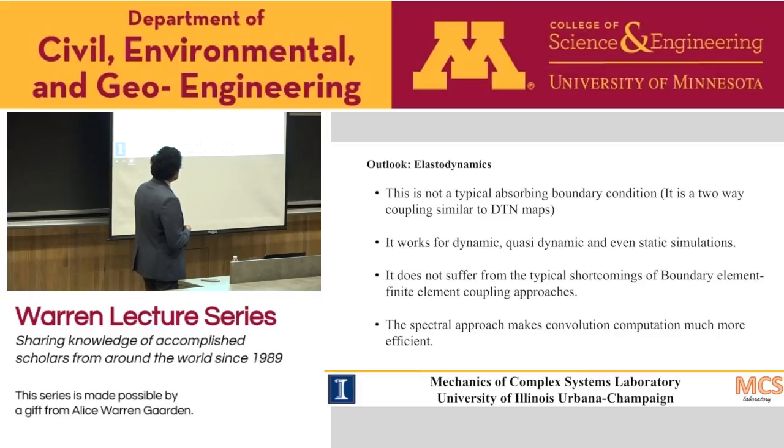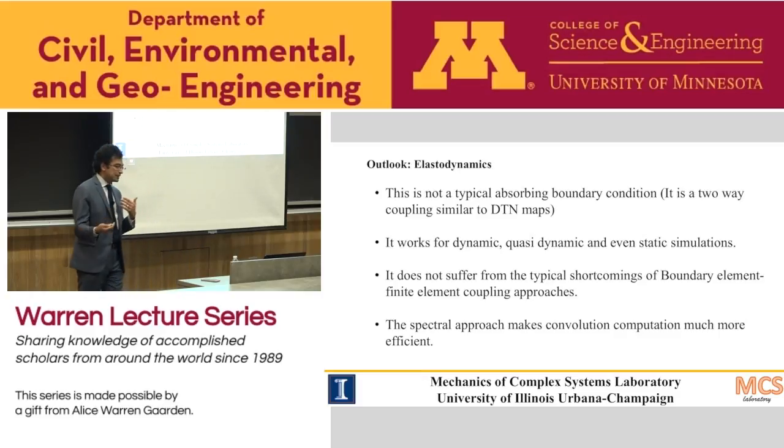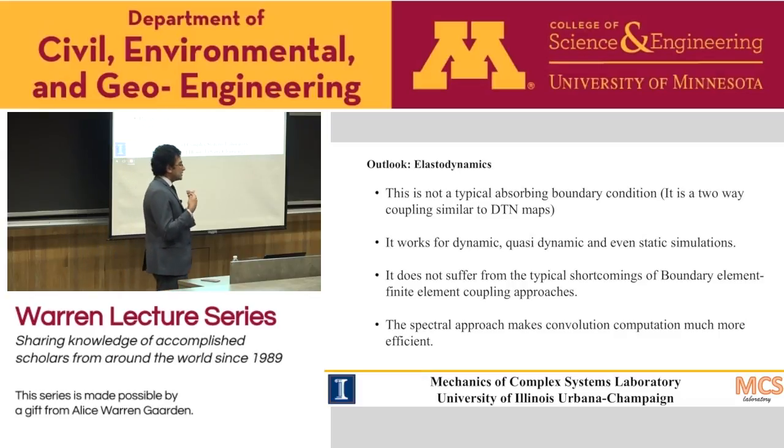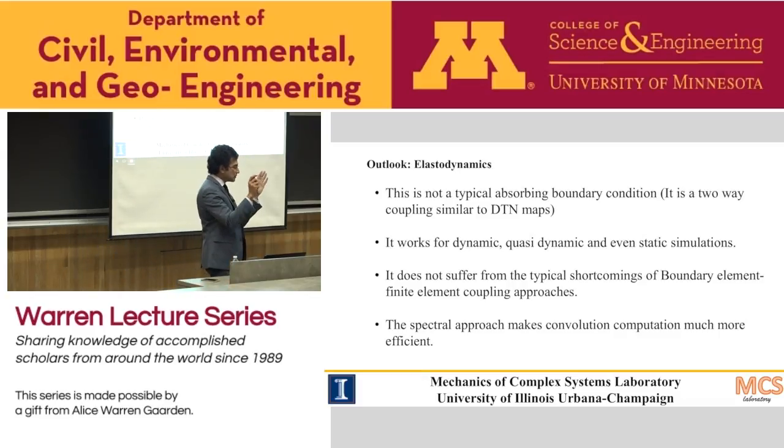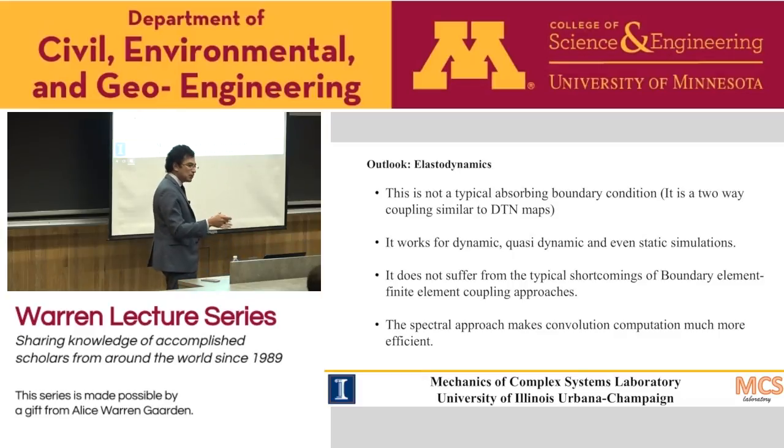People have tried coupling finite element with boundary element, but if you do that in the time domain, it's very challenging because your stiffness matrix becomes non-local and not banded. So you have a populated stiffness matrix. And then the spectral approach makes convolution very promising.